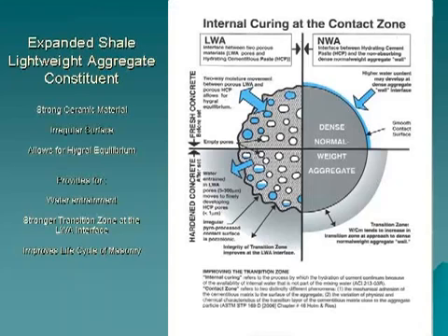This graphic reminds us of the discussion we had earlier of the nature of lightweight aggregate particles and their ability to absorb water. ESCS is no exception, although it absorbs water more slowly than many other types of lightweight aggregates. This absorbed water is a benefit that provides curing internally. The graphic in the slide compares a lightweight particle to a normal weight particle. The top half of the graphic depicts what is going on while the concrete is fresh, and the bottom half relates to hardened concrete.